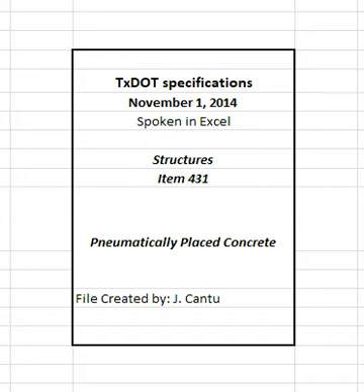Achieve SSD conditions by high-pressure water blasting 15 to 30 minutes before placing the repair material, soaking a minimum of 12 hours, or by other approved methods. An SSD condition is achieved when the surface remains damp when exposed to sunlight for 15 minutes.